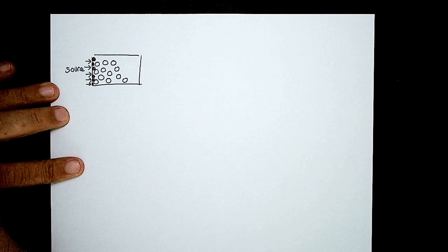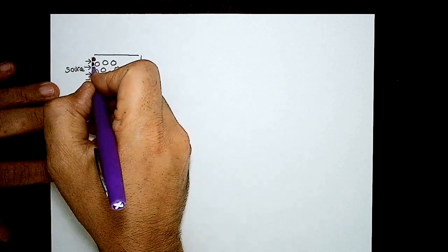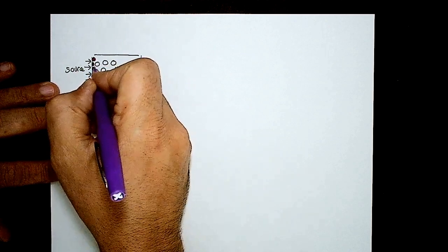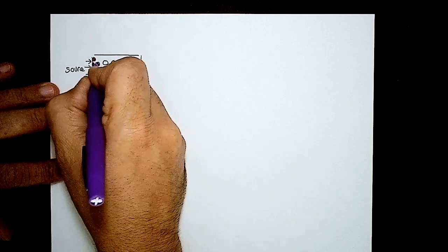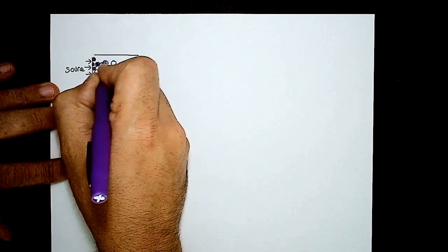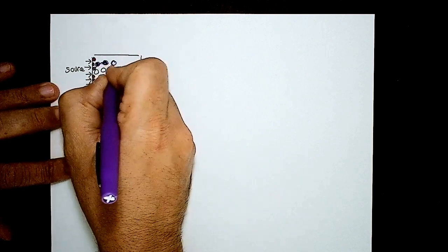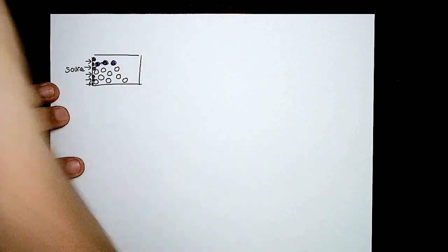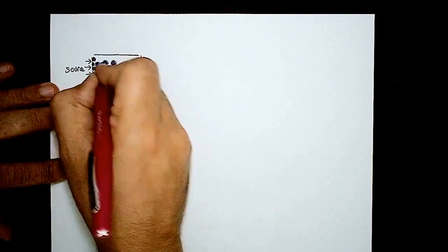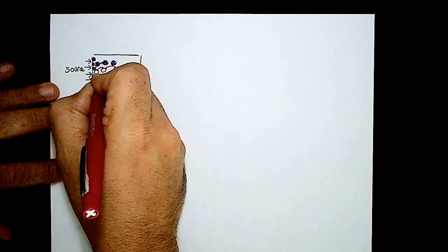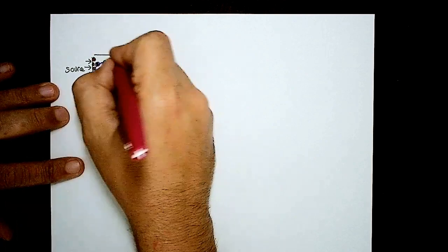When you have free electrons, these electrons are free to move, right? So they can actually move, correct? So what's happening is these molecules will vibrate. When they vibrate, they're going to make a collision and transport some of the energy to this one. And this one is going to vibrate and transfer by collision some energy here, and so on. The other way is the free electrons in the outer shell will transfer, and these electrons will carry energy to the next one. So we have either the vibration,